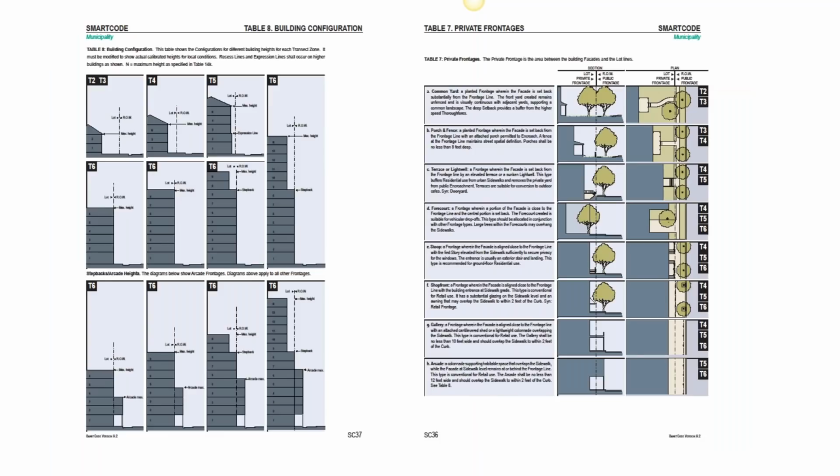So at a high level, we go about defining these areas, and then from that, we use those transects to drive how these buildings take shape. So not so much whether this can be a business or a residence here. It's more about the shape, and that follows what it actually is. So we determine things like setbacks, minimum and maximum floor heights, and we even start to shape the actual volume of the space, or the massing. So setting it back, whether it has a balustrade, a balcony, a promenade on the first floor, and even getting into plantings and everything else.